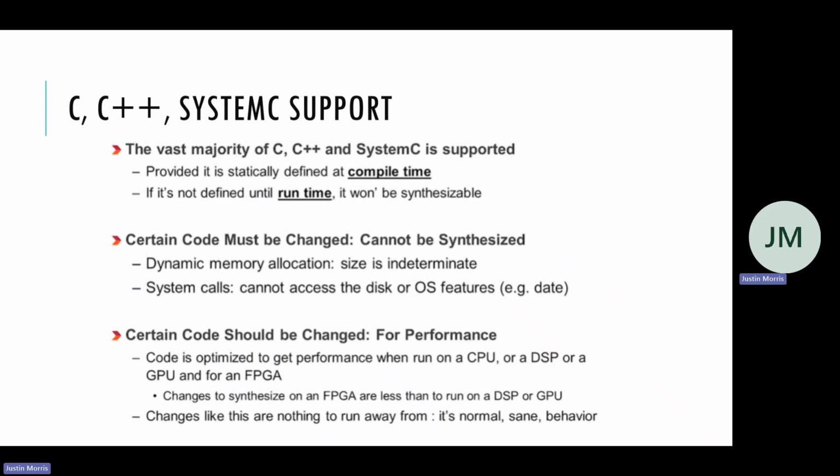And it's provided statically and defined at compile time. If it's not defined until runtime, like pointers, right? Pointers are dynamically sized at runtime. It's not synthesizable by the HLS tool. The HLS tool will not be able to give you outputs of a hardware design for that because it needs to know exactly how big things need to be, right? If it can be dynamic in size, it doesn't know how big it needs to be.